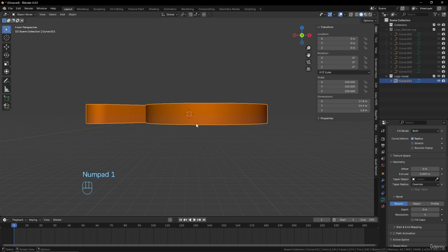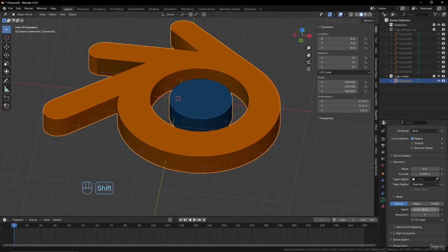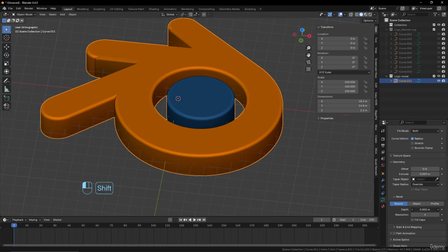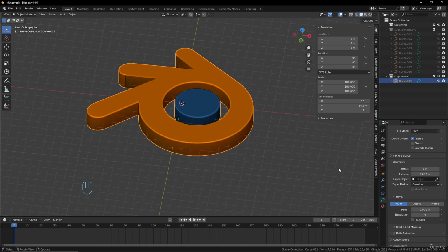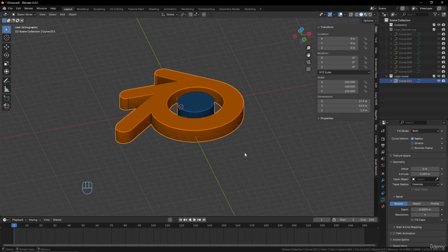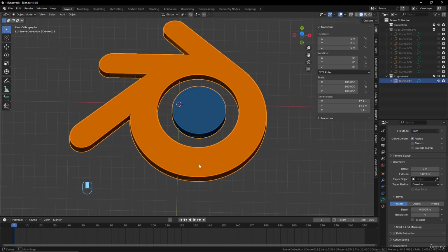I will put it on the ground, and maybe add just before it, I will just add just a little of bevel, just a bit, just like this, not a lot, just to have a nice bevel over there. Maybe just half of it, 0.0005 might be good in my opinion here. Okay, like this, just to have something but not too big.